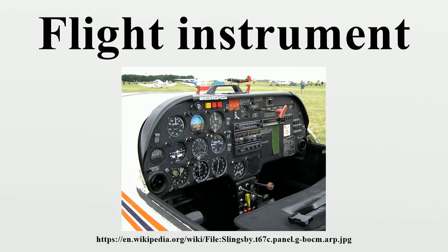Additionally, the compass is subject to dip errors. While reliable in steady level flight, it can give confusing indications when turning, climbing, descending, or accelerating due to the inclination of the Earth's magnetic field. For this reason, the heading indicator is also used for aircraft operation, but periodically calibrated against the compass.